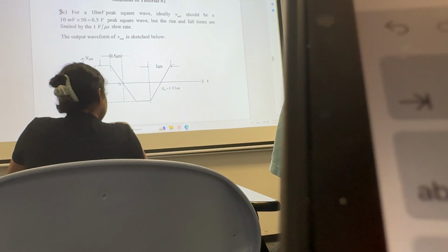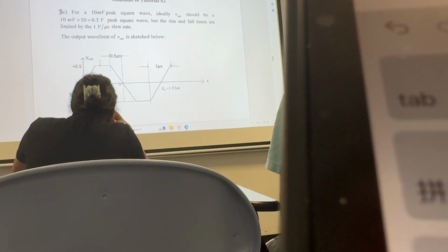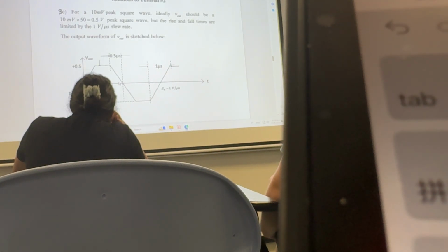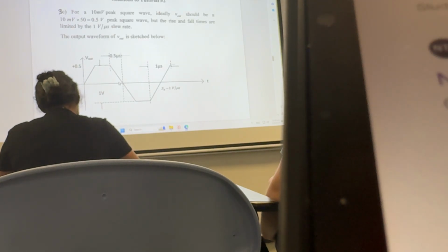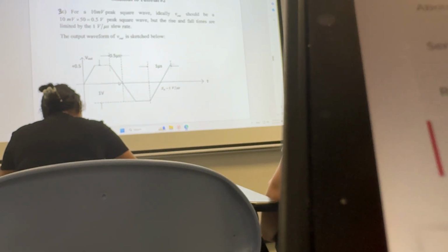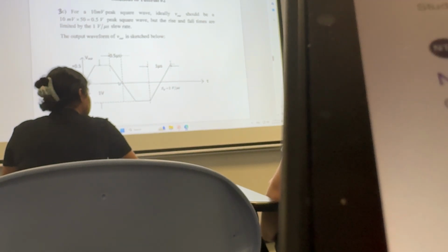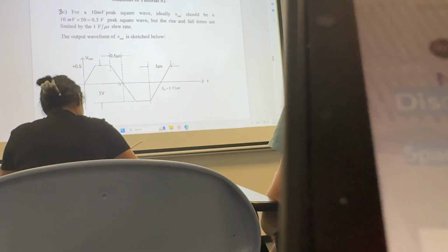Now remember that if you look at the response, you should have infinite slew rate to respond to a pulse, right? But are you able to hit the infinite response? No way, right? You're limited by the slew rate effect, right? So at the end, it's a trapezoidal. Okay? So your output response is from square becoming a trapezoidal, right?